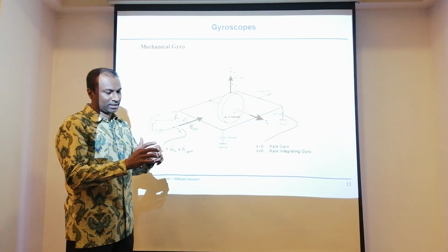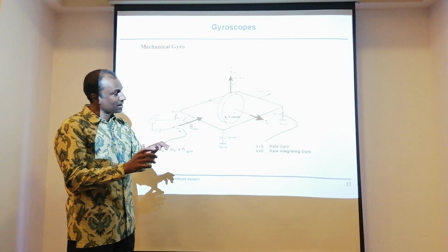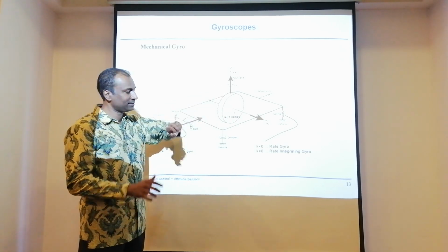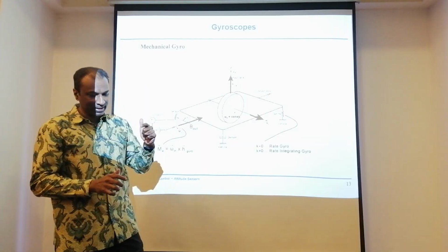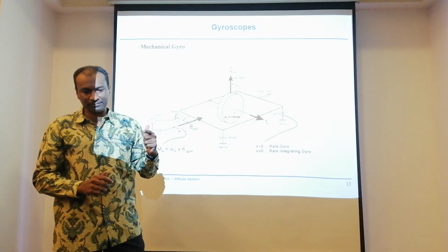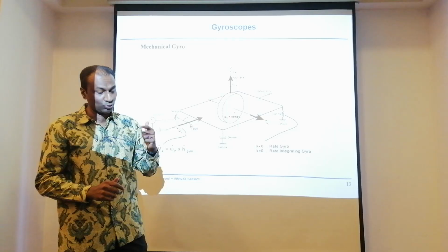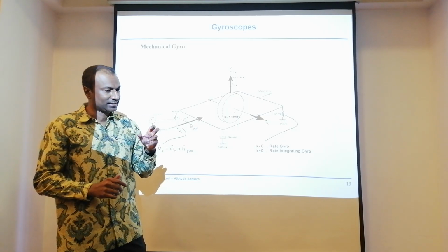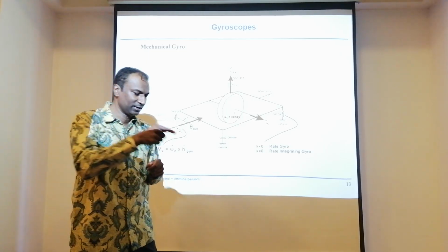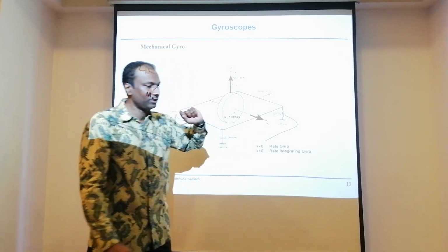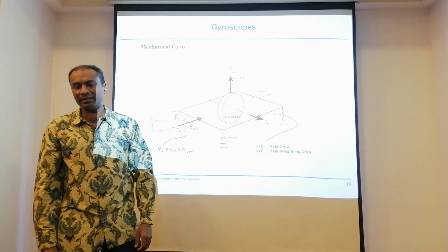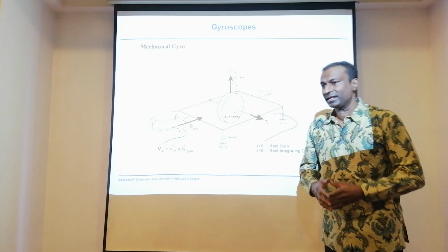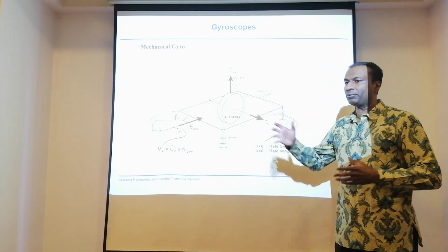So as you can see, you embark the mechanical gyro on the Z axis to determine the exact disturbance, to experience the disturbance torque along that particular axis, but the exact deviation that you have is on the perpendicular axis. So that's how the mechanical gyro works. But we can escalate the mechanical gyro through the fiber optics gyro.